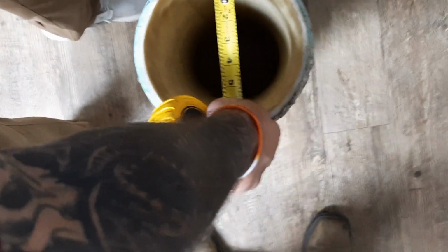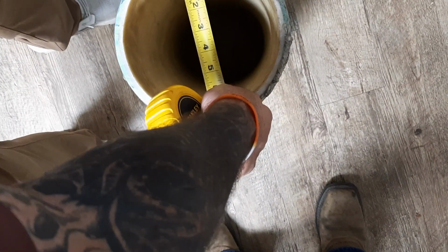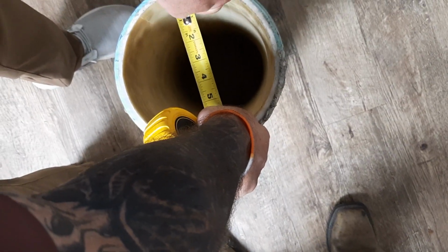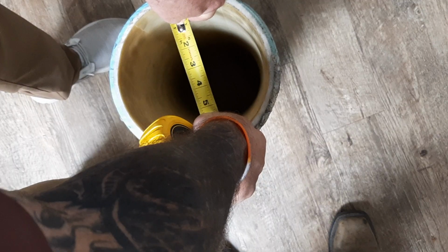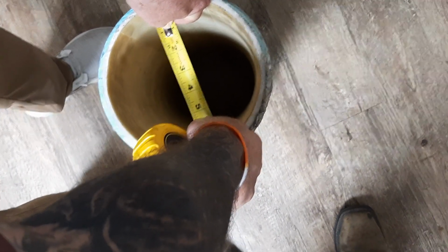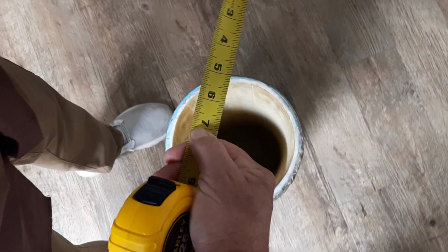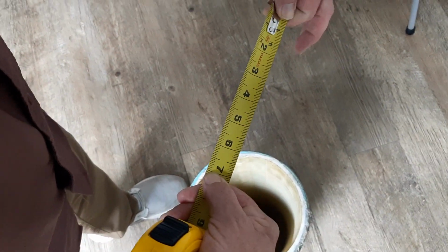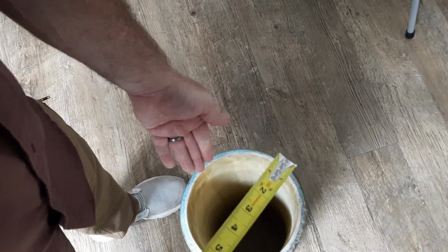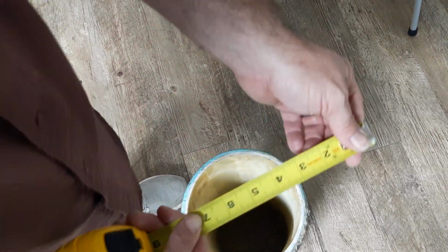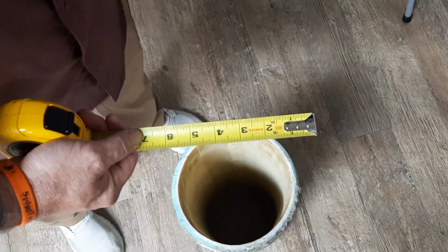You always want to check for a bell. There's no bell on this. And you want to press and get pressure of that tape measure against the top of the pipe. And carefully remove your tape measure without letting your thumb slide, and you'll see that I'm sitting here at 7 inches even. Now this is a PVC pipe that's already been lined. All right, so now that's one measurement.